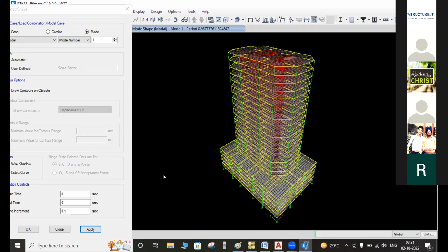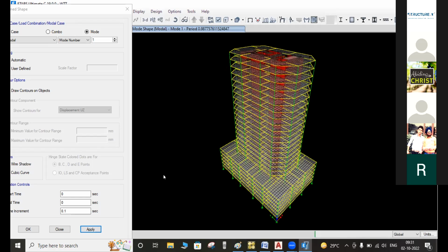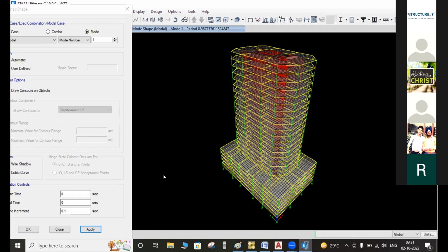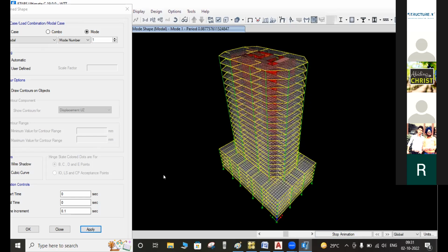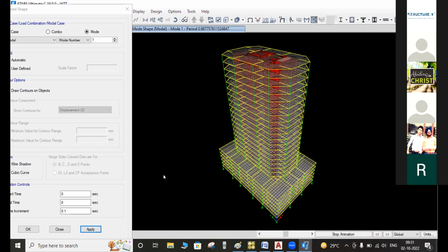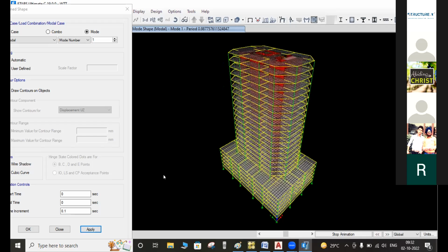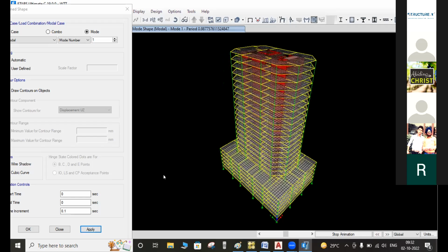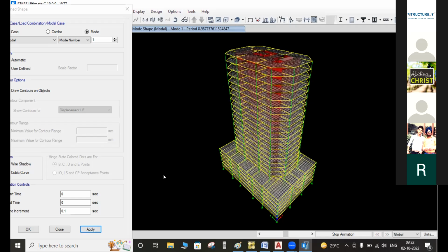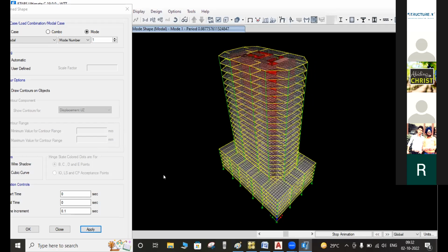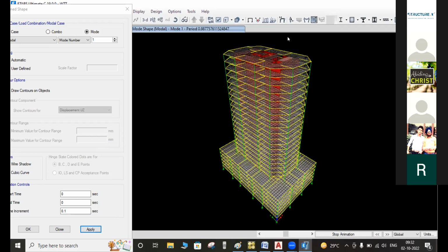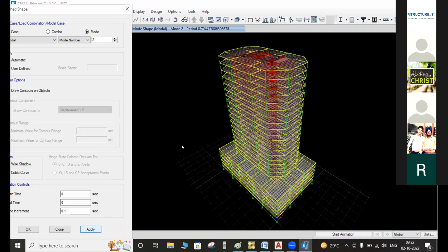Okay, so this is the first mode. Here we have linear translational, right, Karim? Yes, not rotational. Okay, so Mr. Balam, that was some Windows error. So the first mode is linear translational. Got it? Sir, basically we are considering self-weight, and these models are already prepared. All the other analyses, like P-delta and buckling, are included. When we start, we only consider the self-weight, sir. So this is the first mode of vibration. Similarly, we can check the second mode, right, Karim?